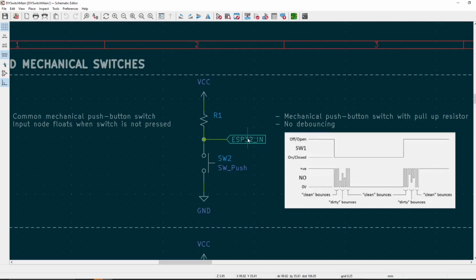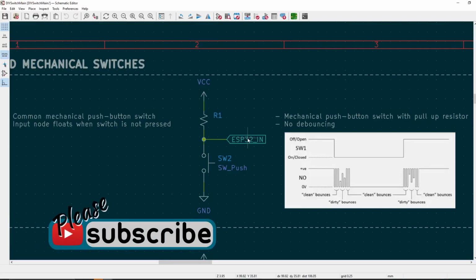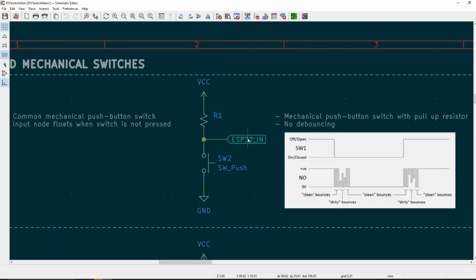And now we are coming to the point that I would like to make with this video. I'm not saying that this is right or wrong, but I'm saying that I didn't see anything like this on the internet. If we are creating a custom PCB and custom layout for our keyboard or macropad, and if we are using a small number of keys, maybe it's a good thing to implement some kind of debouncing in the hardware. In existing projects, the debouncing is mostly done inside the software.